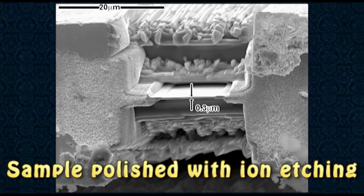A third process exists, which is called ion etching. In this process, an inert gas is passed through an electric field in order to generate a plasma stream, which is then directed at the surface of the specimen. The typical rate of progress that this method produces is wearing the specimen down by a few micrometers per hour. Because of this slow rate, this method is most effective in finally polishing a specimen after using one of the